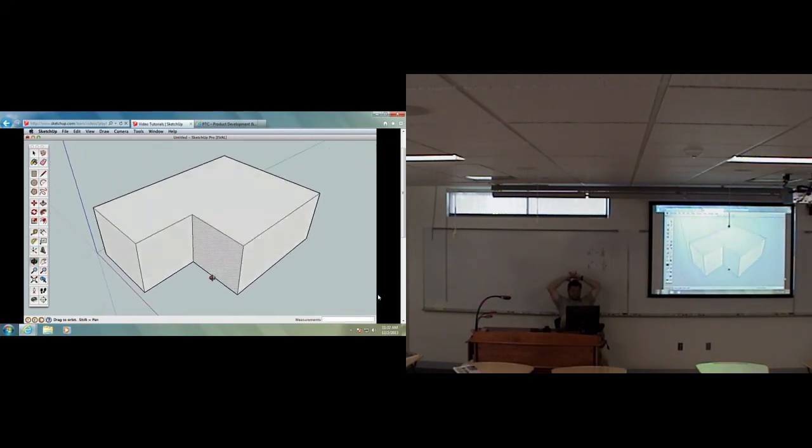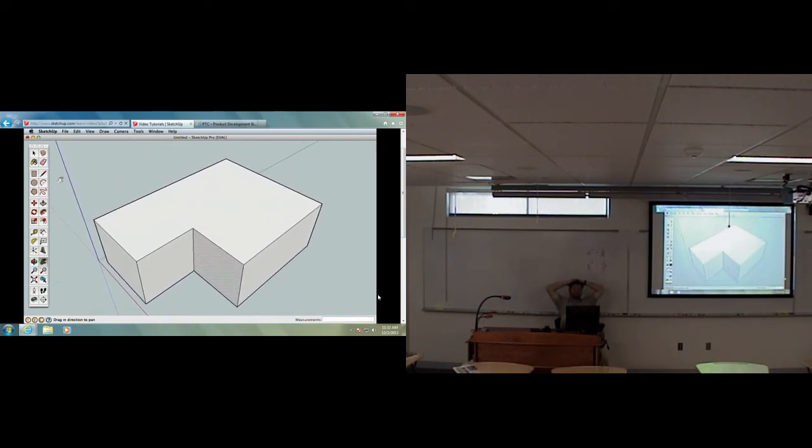To create the roof, we'll use the line tool and draw all the edges we need before pulling the ridge up. Using the line tool, find the midpoint and start drawing back in the green direction. This will be our first ridge, and we need it to connect exactly with the second ridge. To do this, simply hover, but don't click, on the midpoint here, telling SketchUp we are interested in this inference point. Once you see the tool tip telling you it's the midpoint, follow the original.